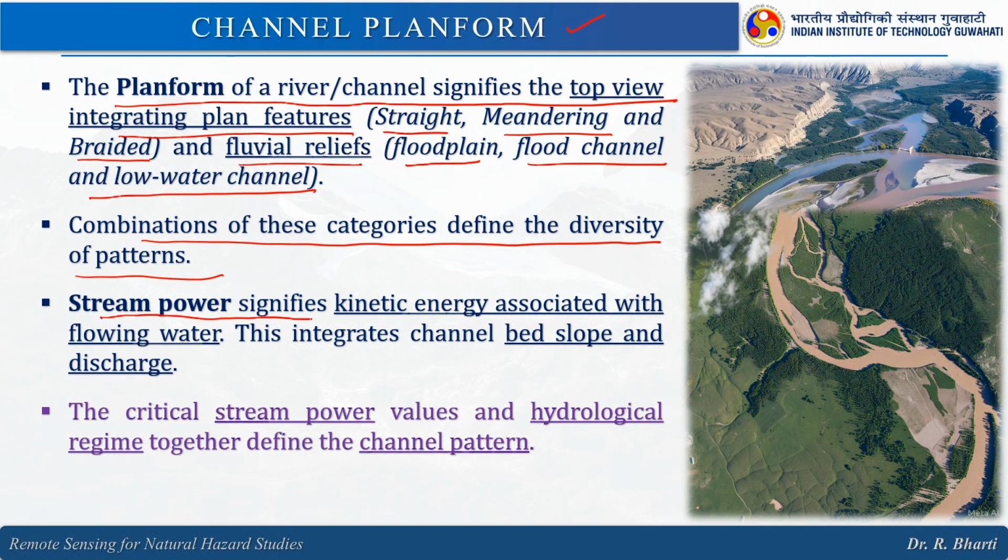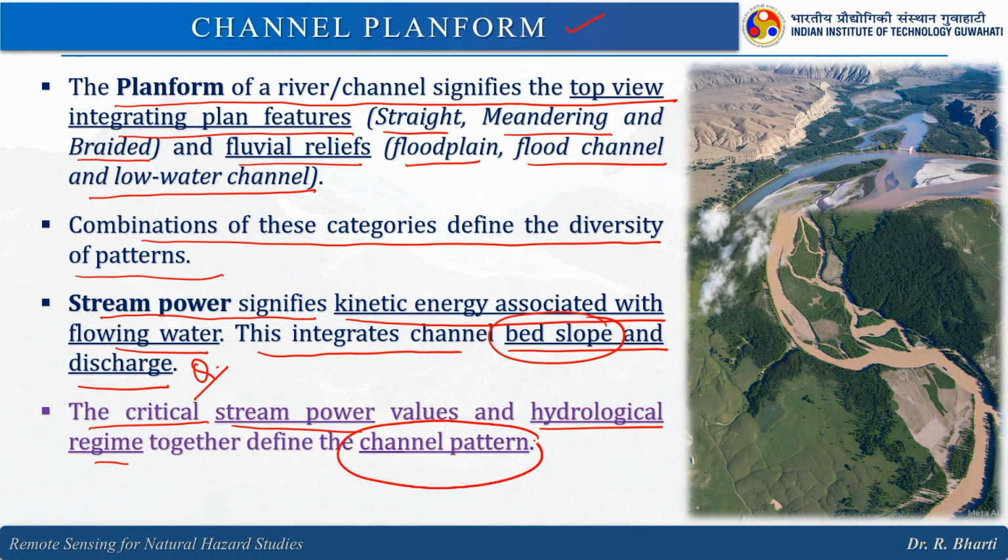Stream power signifies kinetic energy associated with flowing water. This integrates channel bed slope and discharge. So, now the bed slope and the discharge are integrated into this analysis. The critical stream power and the hydrological regime together define the channel pattern.